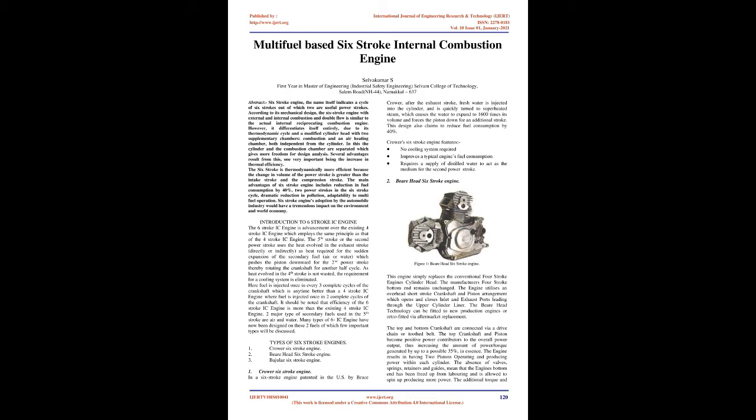However, it differentiates itself entirely due to its thermodynamic cycle and a modified cylinder head with 2 supplementary chambers, a combustion chamber and an air heating chamber, both independent from the cylinder. In this, the cylinder and the combustion chamber are separated, which gives more freedom for design analysis. Several advantages result from this, one very important being the increase in thermal efficiency.